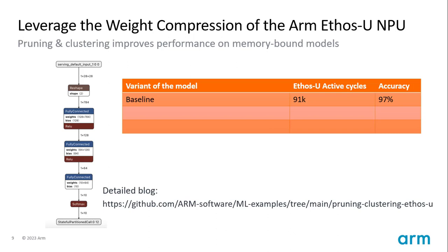And this problem is so important that we even have silicon area dedicated to interact efficiently with the memory. So the Vela compiler is able to compress the sequence of weights. Actually, the Vela compiler is essentially doing the weight compression of your neural network. For example, it's going to compress sequences of 0 weights, and it's also going to compress clusters of the same weights. Then the compressed weight stream is going to be fetched by the hardware and decompressed, and you're going to save a lot on memory accesses.